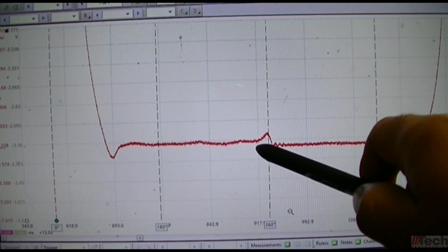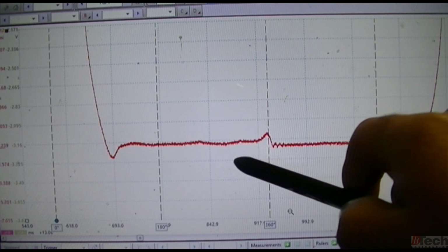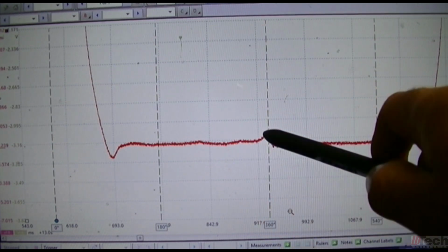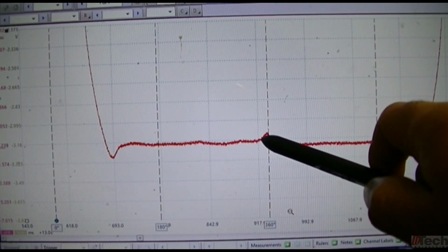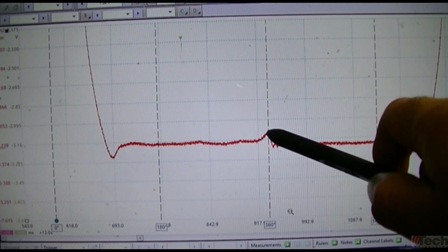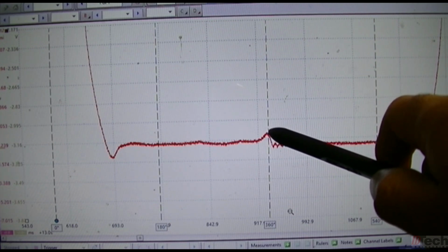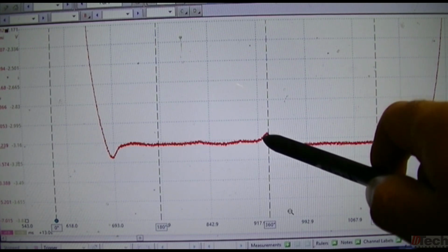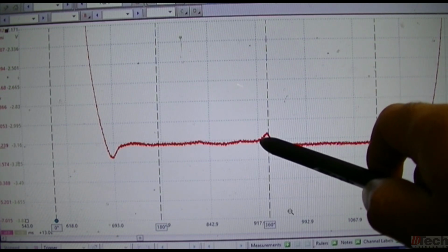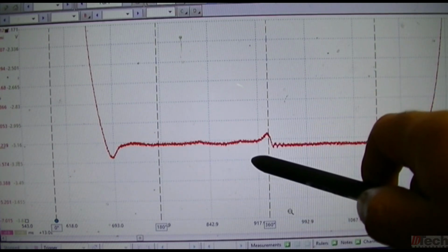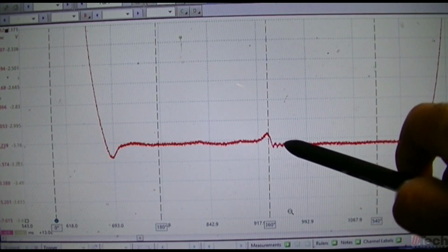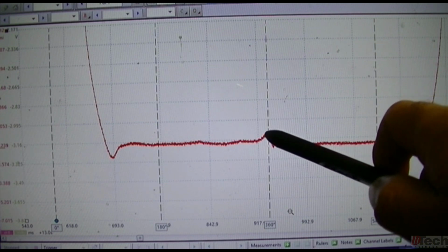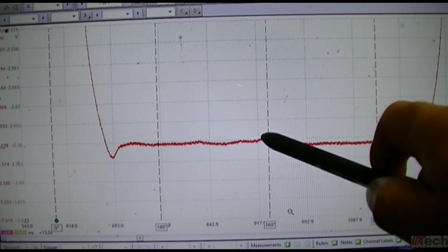Now compared to this good bank, same exhaust stroke, there is a rise in pressure, but it's not as high compared to the bad bank, which most of the time will indicate that the valve was still closed during the exhaust stroke, and no intake valve had opened up to that point yet.